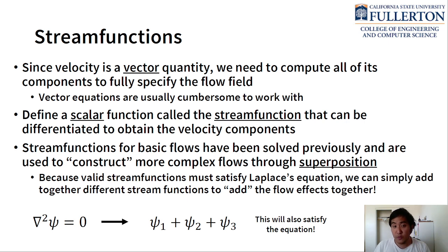And so we define the stream function, which is a scalar function, but if you take certain derivatives of that stream function, you can get the velocity components. What's also special about these stream functions is that they satisfy what's called Laplace's equation, which is right here, a partial differential equation, but most importantly, it's linear. And so for linear equations like this, if you have one function that satisfies it and another function that satisfies it, you can simply add them together, and their sum will also satisfy the original equation as well.